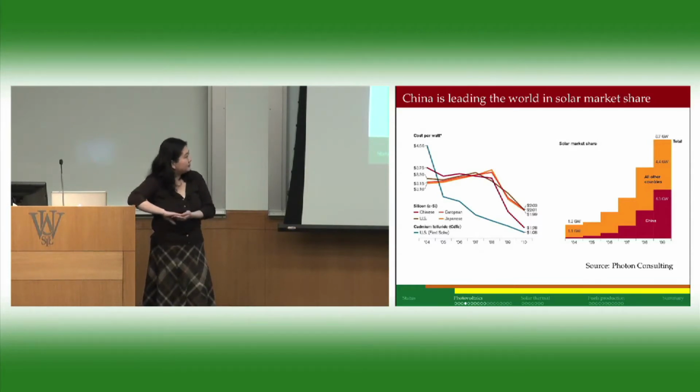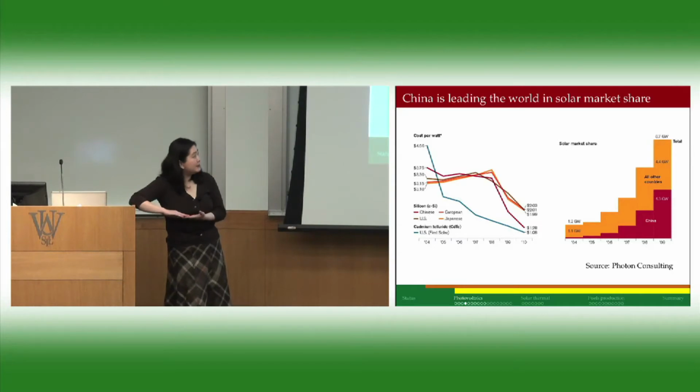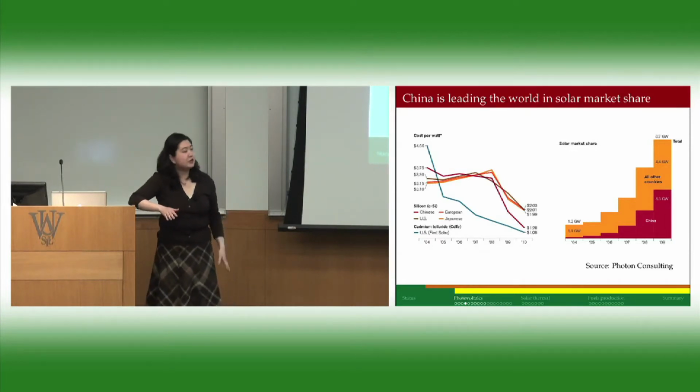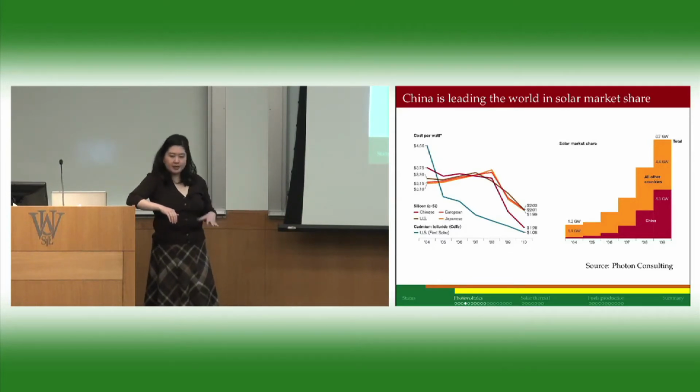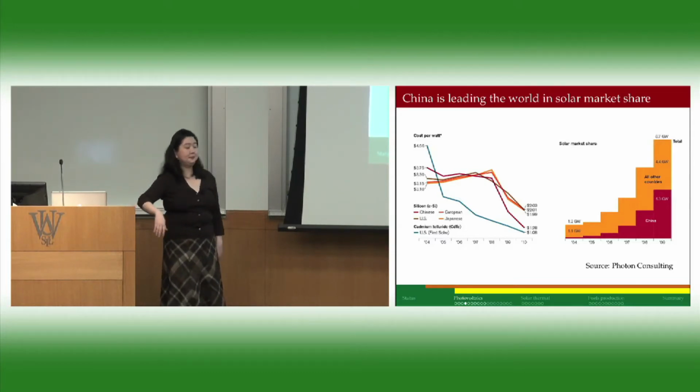And related materials. And the problem with these materials, cadmium telluride, CIGS, etc., is that they're very hard to manufacture on a very large scale. Okay, so even though they may be a lot cheaper, and they have pretty decent efficiencies, almost approaching about 20%, it's actually very hard to manufacture them on a large scale. So for now, I would say that cadmium telluride and other technologies are probably not quite viable yet for large scale manufacturing. So even though you can see about $1 per watt there, it's not really commercially viable on a large scale yet. So silicon is still where it's going to be for a little while.